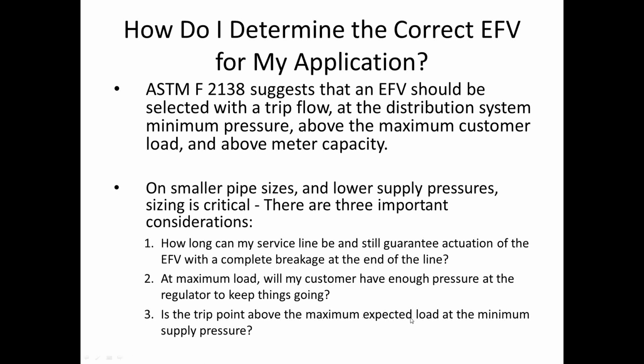Is the trip point above the maximum expected load at the minimum supply pressure? So you want to have that minimum trip point above what your anticipated load is at that minimum system pressure. So those three considerations you need to keep in mind as we're looking to apply a particular device into a particular system. So let's look at that real quick.